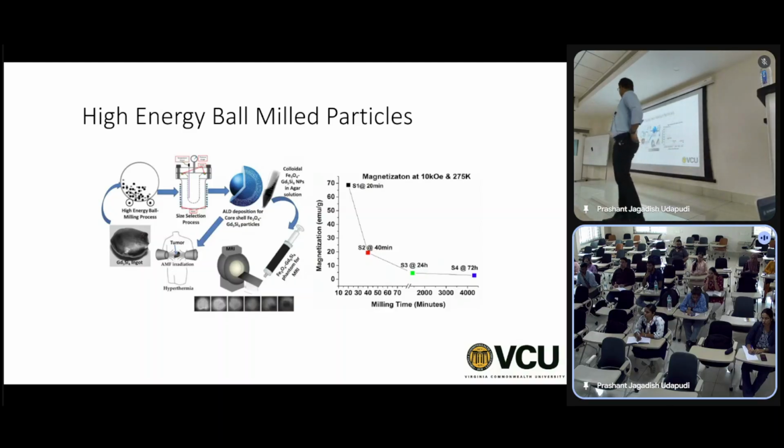Sometimes what happens is, if the melting points are too different, if silicon had a very low melting point, then it may reach its boiling point by the time you melt gadolinium, right? This is not the case here, but if you used germanium or indium, you may reach the boiling point. If you reach the boiling point, some of the vapors go away, right? Then you won't have the same amount of silicon left to make a 5,4 compound, right? Then you get an off-stoichiometric compound. You won't get the same compound, 5,4. So that's one of the issues.